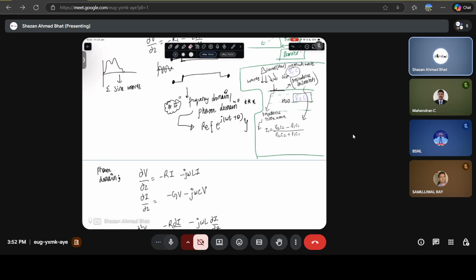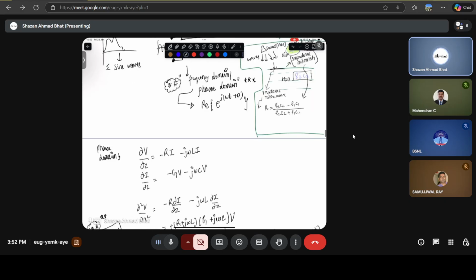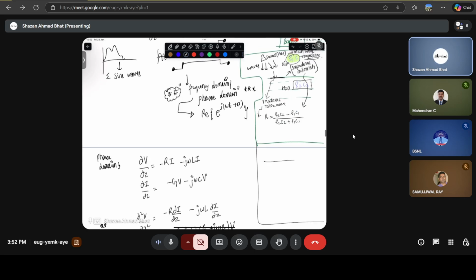And by the way, this is not even impedance, this is basically the reflection coefficient. This product is basically impedance. Okay. So what I mean to say is that if this is water, there is an acoustic wave coming in. You have rho 1 c1, which is basically the impedance of the air. This is the impedance of air to the acoustic wave. Then you have Z2, which is basically rho 2 c2. This is the impedance of water for the acoustic wave.